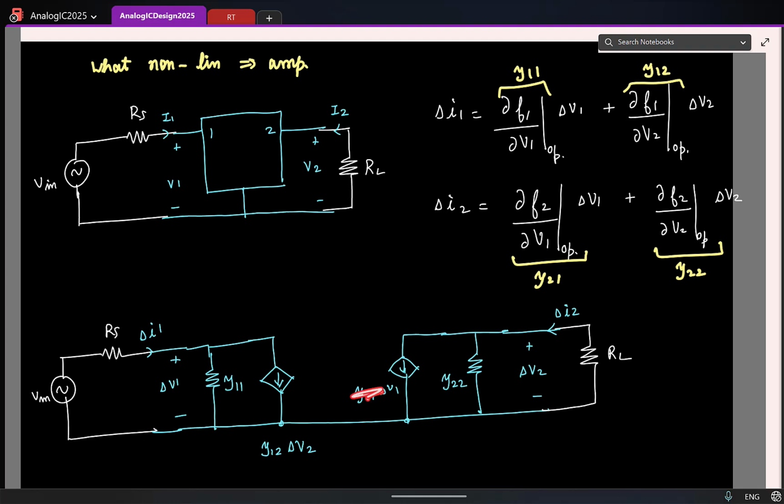Okay, so now of course, let me write this clearly. Basically again our goal is the following. I want to find what the nonlinear characteristic should be. I can find the small signal gain from the input to the output. I can solve this linear circuit and get an expression for the gain, and the gain will depend on all the Y parameters.